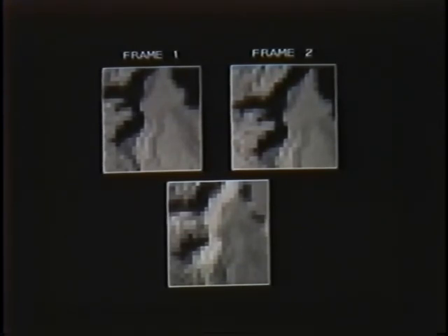In order to quantitatively evaluate the clutter leakage, we will relate it to the standard deviation of the image intensity in the difference frame. A high standard deviation implies a large clutter leakage, while a small standard deviation implies a small clutter leakage. The standard deviation here, sigma, is almost 3,000, which is very high considering that the total range of the data is only about 12,000. This, along with the clutter leakage, tells us that these two frames are not very similar at all.